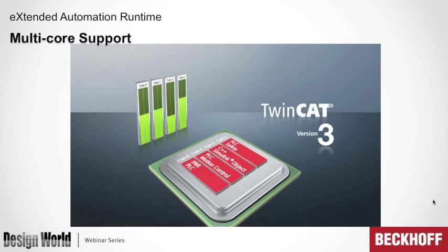And with that in mind, we're thinking, okay, I got all this nailed. What else can I do? And things like condition monitoring are becoming real. What condition monitoring is, okay, I have vibration sensors on a bearing. I take that as input, I sample them at a very high rate, I run them through a Fourier transform, and I look at the frequencies. And I look at this over time, and I can look for maybe a particular frequency crops up that wasn't there before, and it's an early indication of a mechanical wear, a mechanical breakdown.